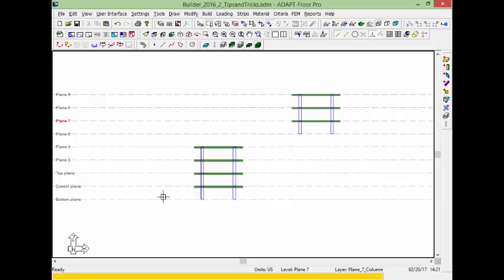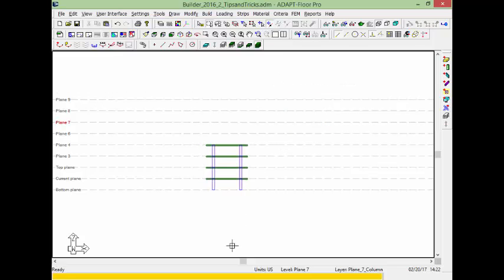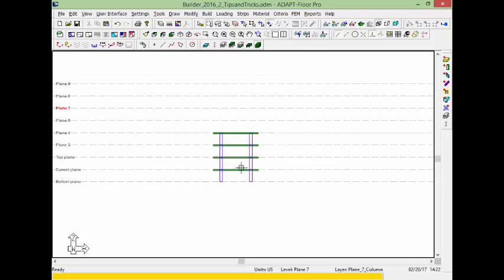In this example, my current plane when I selected the components was here. I have 3 levels above that. I inserted that at level 7, and again we have a leftover level that can't be assigned because there's no reference plane above 9. So we'll go back and delete that, and we'll give one more example where we keep the reference plane. Again, we'll go back to current plane,